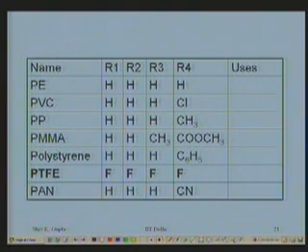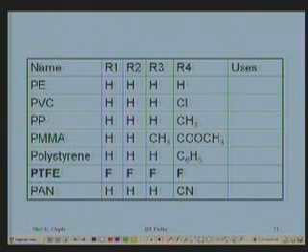The only thing is, its fabrication is a problem, because the softening temperature is around 375, and fluorine is a very reactive material. Hydrofluoric acid, which forms, is a very reactive material. The container in which you have to keep it is a problem. Anyway, we do have a lot of manufacturing going on for Teflon these days, and we make use of it.